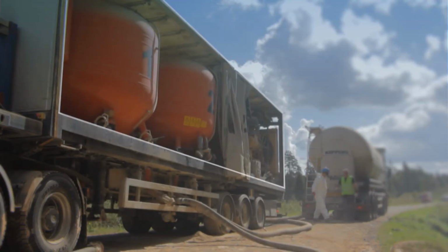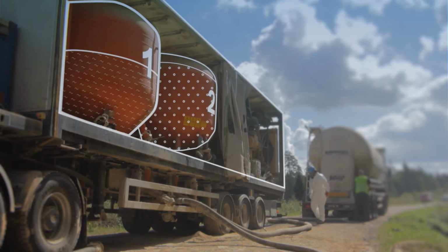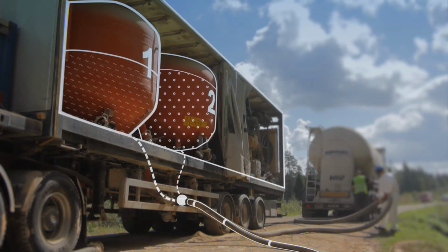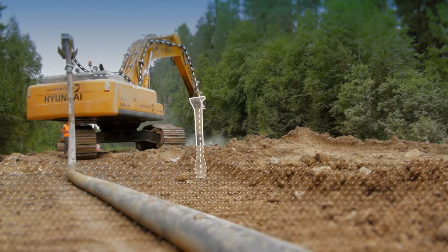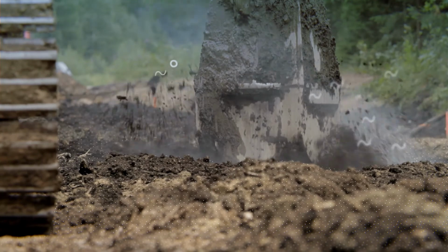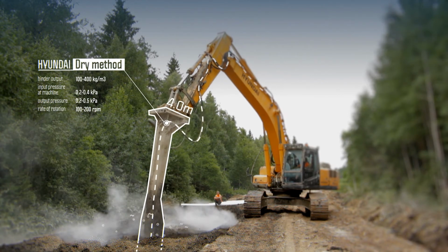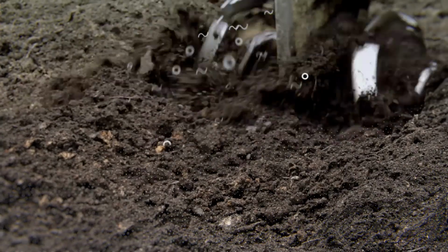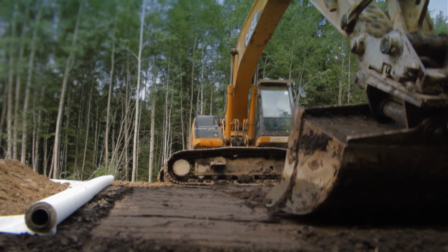The needed components for mass stabilization, oil shale ash and cement, were stored in 2 tanks. These substances, stored in containers, were passed through a mixer and into the subsoil. For the injection of binding substances into the subsoil, Finnish specialists were on hand to help, applying their years of experience and application expertise to the project. The binding substance was pressed into the subsoil at a depth of up to 4 meters by the mixer, thus ensuring even distribution of the mixture. Processed layers were flattened by a dig bucket and prepared for the next stage.